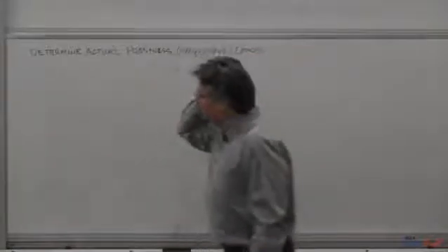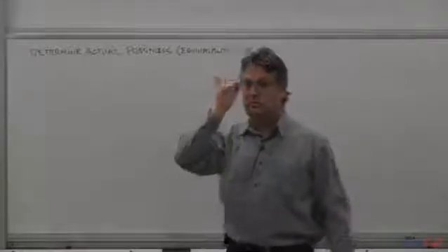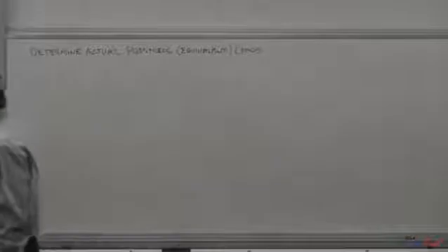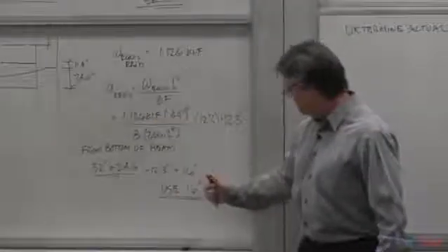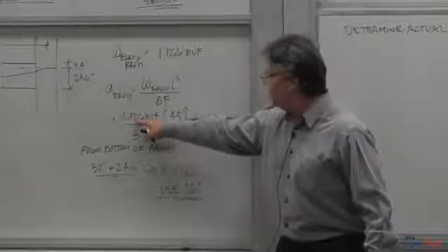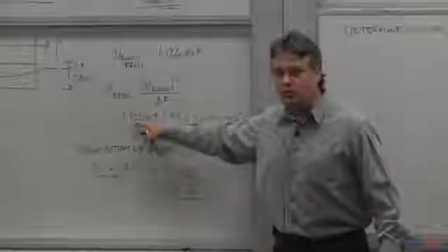Okay, I can't stress this enough, and I keep stressing it because people will make these mistakes. This was an estimate of the equivalent load. Then I came up with a number. You may round this number. You may decide to jockey this number. So when you do that, unless this, like mine, turned out to be exactly a round number, this is no longer your equivalent load. So don't use your estimated approximate equivalent loads for your calculations.